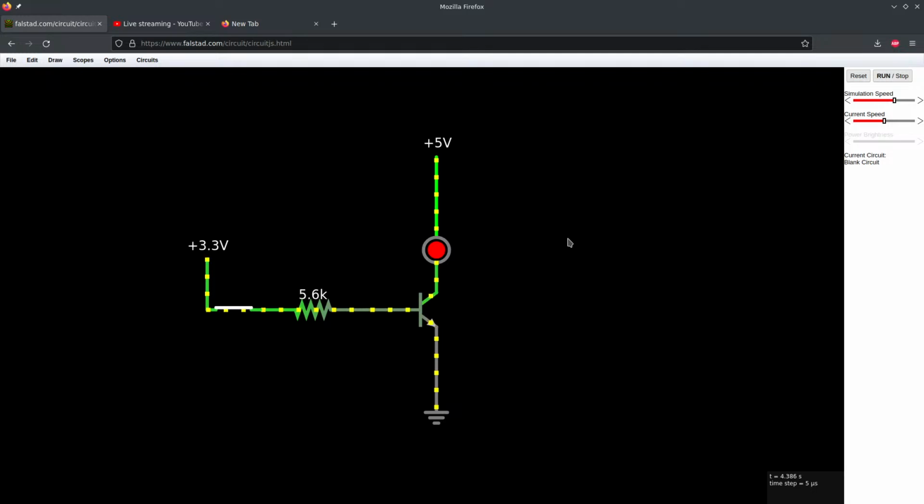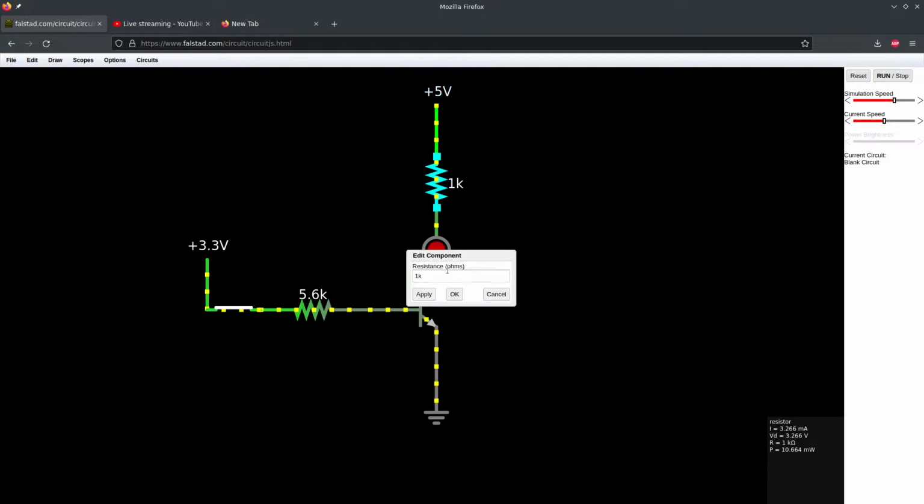So you can sort of see there's barely any current flowing right here with the little dots. But over here, there's a ton of current flowing through this LED right now. We still need, and we still should have, a resistor for the LED, according to what we want. So we were saying 470, but now that we're not driving it directly from the MCU, we can do 220 ohms. And, okay, it looks like that's just a little bit high at 5 volts. So I'm going to do 330. There we go. That's another standard size.